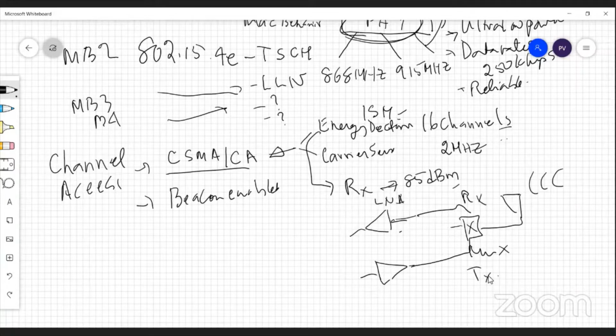So once you switch on the state machine to get the data in the reception mode, you see the energy on that system. Supposing you find that it is at minus 60 dBm, and your receiver sensitivity is at minus 85 dBm. Let's say, for ease, I'll make it at minus 65. You have an energy which is 20 dB higher than the receiver floor.